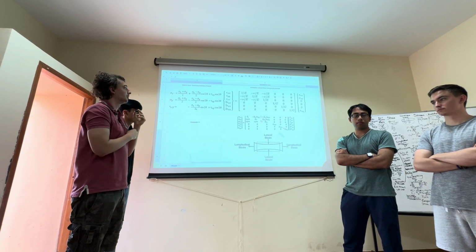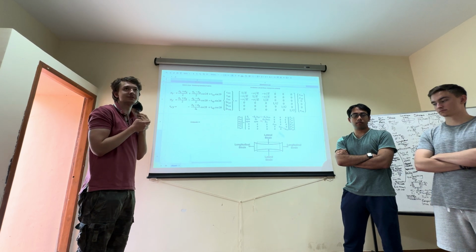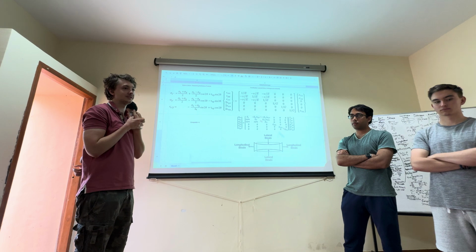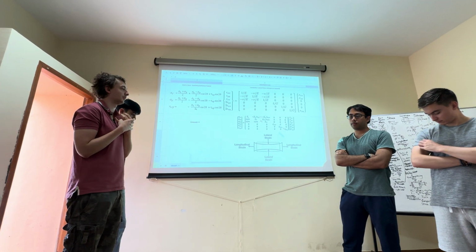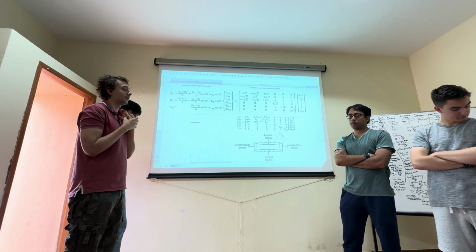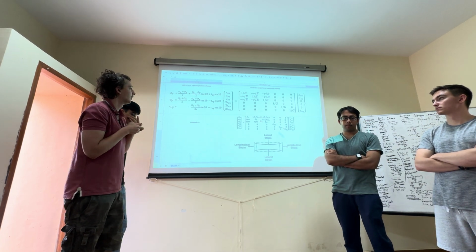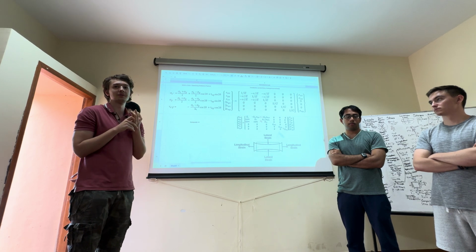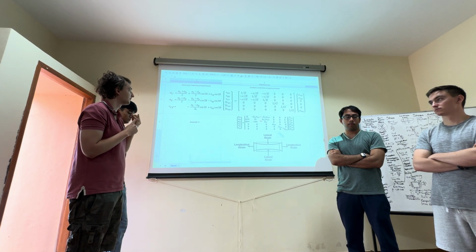This assumption cannot be used for composites, since we want to look primarily at shear stresses and analyze them, and also from experience they're usually not 0, hence we need to include them. But in the end we have only 5 unknowns, so we can still analyze it well enough, and computing power is strong enough that we can solve it in its current state.